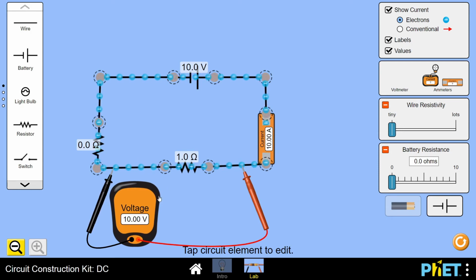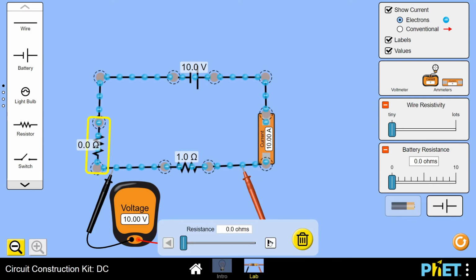We can now use our variable resistor to take some readings for our 1 ohm fixed resistor. To take readings, we first set the variable resistor to give the highest potential difference and record the readings on the voltmeter and ammeter. We then adjust the variable resistor to change the potential difference across our component. We will record the new readings on the voltmeter and ammeter and then repeat the measurements, adjusting the variable resistor to decrease the potential difference slightly each time. The resistance is easily altered by clicking on the component and using the sliding scale.